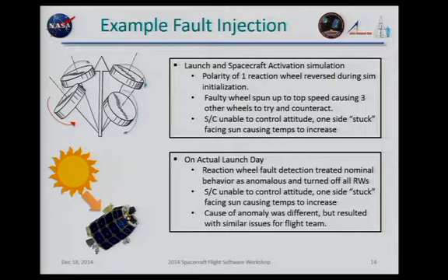This caused the thermal team to get a little bit nervous. We're supposed to be slowly rotating around to keep the temperatures nice and uniform. So we want to quickly diagnose the problem. If it's a software fix, that usually takes a while. So the team's reaction, which was the correct one, was to just power off that bad reaction wheel and let you have three wheels controlling the attitude. It's not as good as four-wheel control, but at least you're spinning and you get out of this critical event.